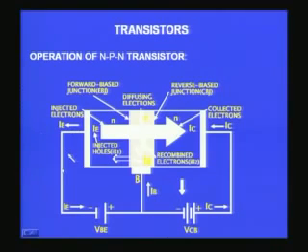So there will be a large current flow here, a finite small current into the base, and a large current flowing into the collector, again because most of the electrons coming into the base are collected by the collector, and therefore there will be electron flow into this. Almost 90% of all the electrons emitted into the base will come to the collector, therefore there will be a large flow of electrons here which corresponds to a current in the opposite direction.